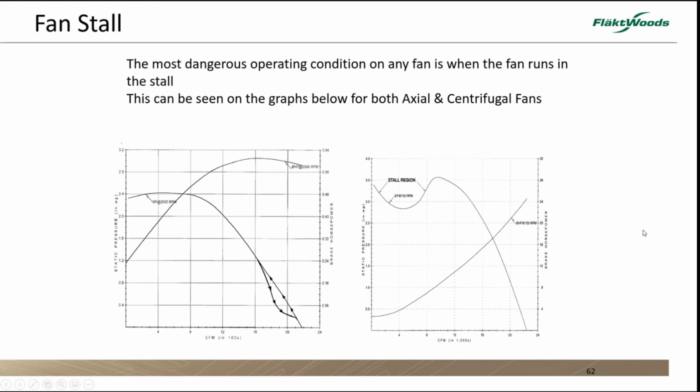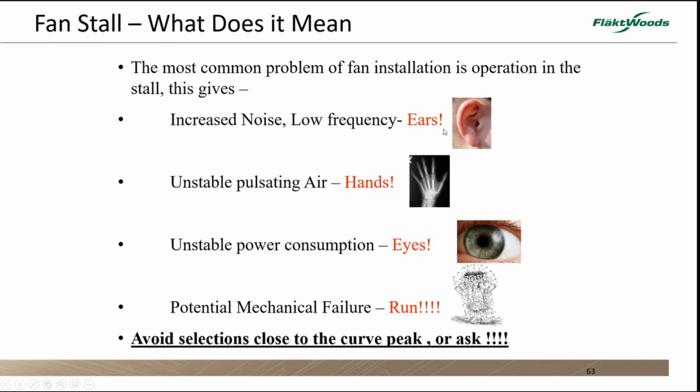What does that mean? Well, it's an exaggeration, of course, but it's increased noise, low level. You can hear that. If you put your hand in the air after a fan, under normal circumstances, it's like a smooth force. When it's installed, you'll get severe pulsation. If you look at the absorbed power, you'll see that it fluctuates. So, be careful, because that probably is the cause of more failures than anything else in fan use. That will be different modes of fans. With our fan product range, we know how fast you can run the impellers forward, we know how fast you can run them in reverse, and we know how fast you can run them in the stall. So just make sure you ask if you've got a dedicated requirement.